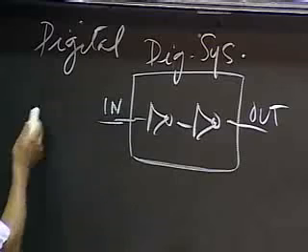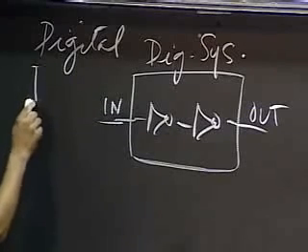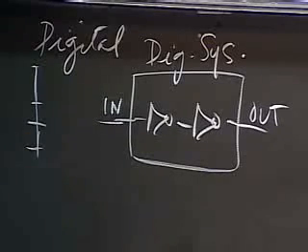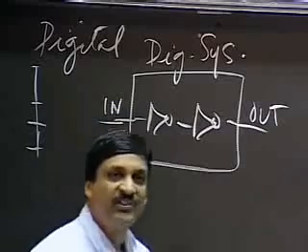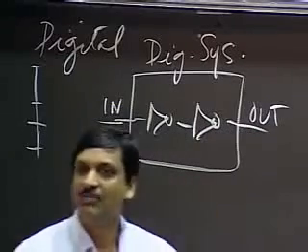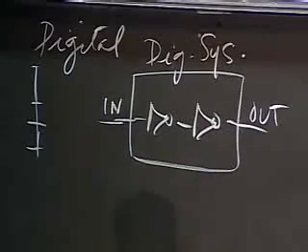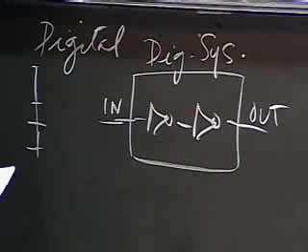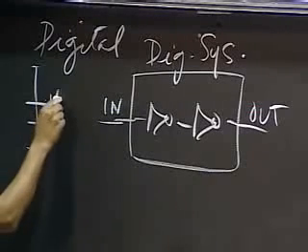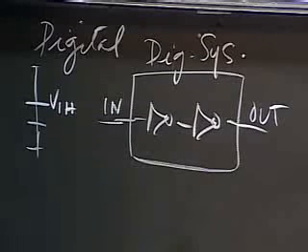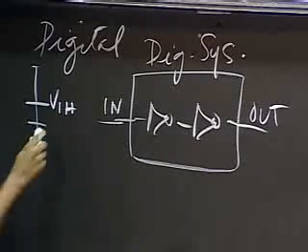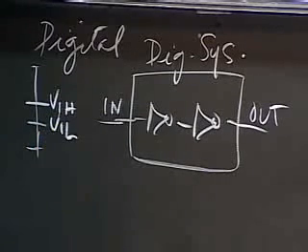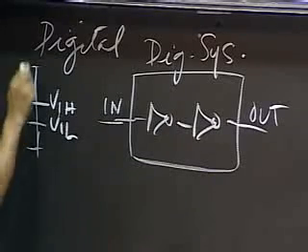And the discipline we described comprised signals adhering to certain voltage thresholds, so that all the components in the system could agree on what comprised a 0 and what comprised a 1. Okay? So the way we did that was we said that we would have a threshold called VIH, V input high, another threshold called VIL, V input low.